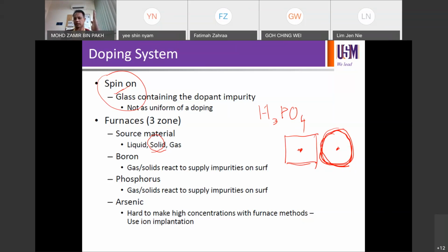Your nitrogen comes from the back to send the precursor material in the direction of your wafers, and then you can get doping as well. The concept is the same as POCl3, except that there we send phosphorus vapor onto the surface of your silicon, but in this case you use a solid source dopant instead of liquid. So it is possible too.